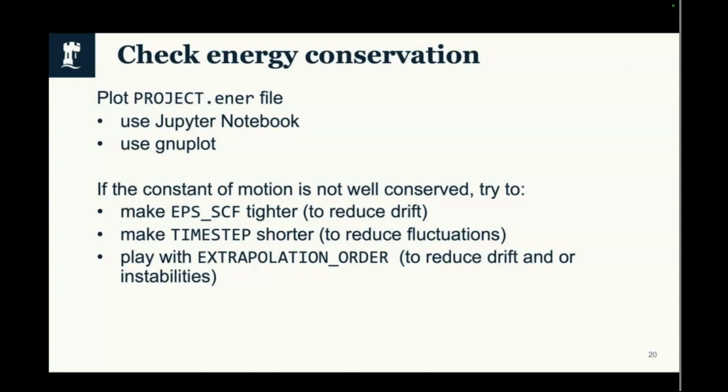If your simulation does not work well, you have to go back and, say, make your convergence criteria tighter, for example, decrease your time step, and also play with this parameter.